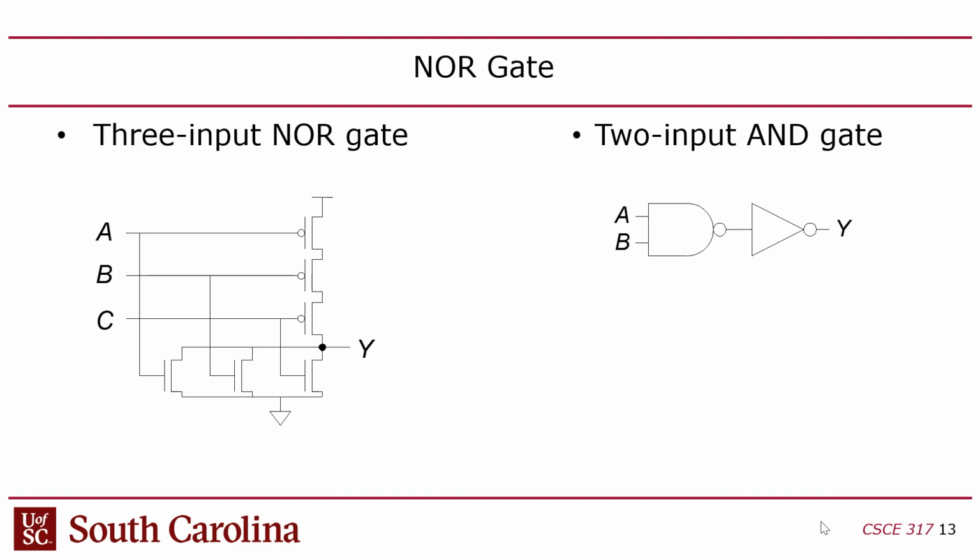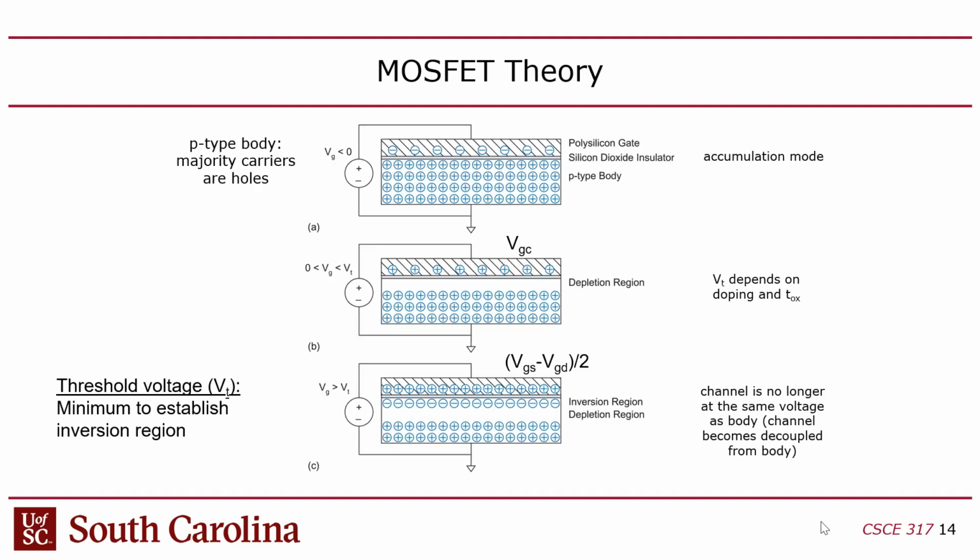All 3 of these have to be 0, which will create a path through these 3 transistors in series, and it will likewise turn off all 3 transistors in parallel, right? But if at least one of the inputs is 1, then that'll be enough to pull down to 0 and disconnect the series of 3 transistors there. Does that make sense?